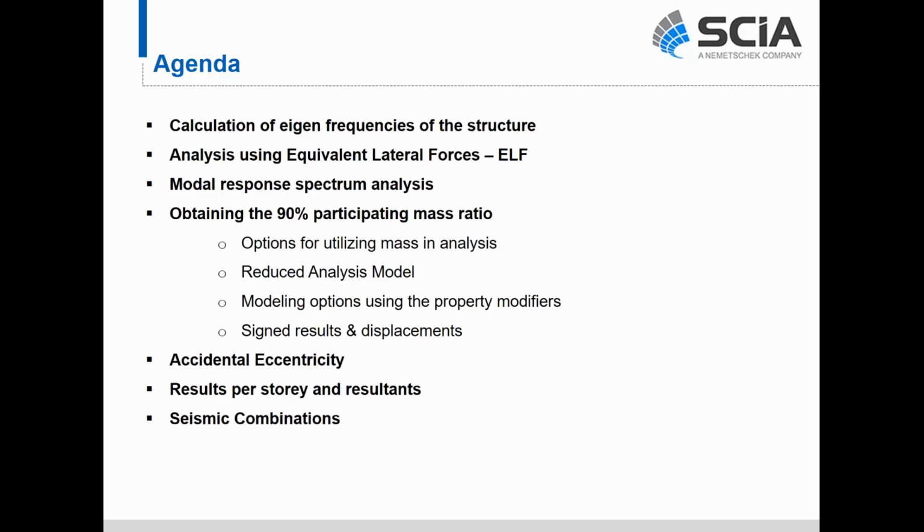So, a little agenda for today. Today we really want to focus on seismic analysis. We'll talk about the different calculation approaches of eigenfrequencies on the structure. We'll talk about analysis using the equivalent lateral force procedure, which is very widely used here in the United States. We'll talk a little bit about the modal response spectrum analysis. One of the most important things about seismic analysis and a requirement of code is obtaining 90% mass participation, so we'll talk about a few different ways that SCIA handles that. We'll also talk about accidental eccentricity, results per story, results for seismic loads, and then finally seismic combinations.